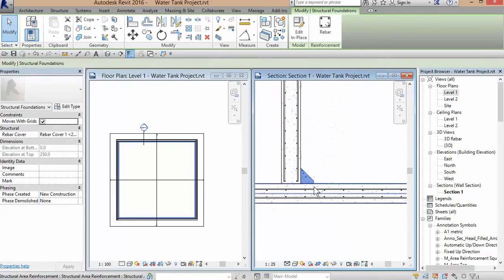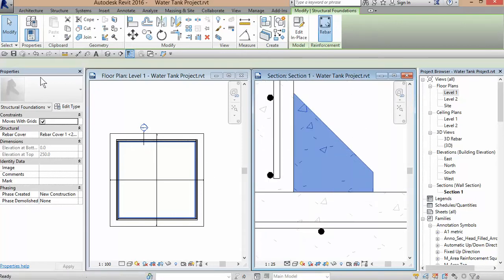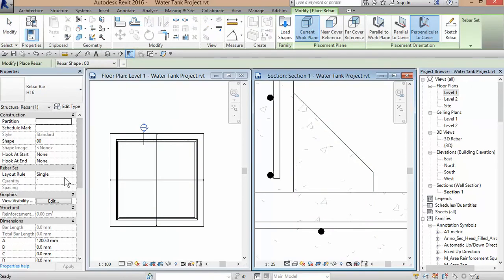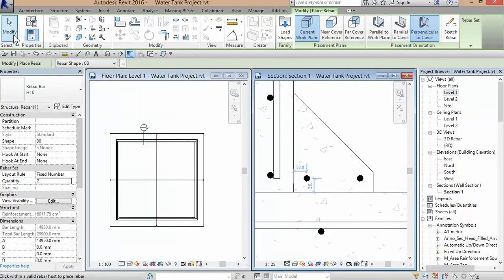any section, you can select. Now mind you, when I'm adding rebars to here, it's only going to be going along the top horizontal part and not straight around. If you choose, you could create sections and add the rebars along the full part, but for now I'm just going to do it along here, and I will only display the rebar here for documentation purposes. So select rebar, same 16 millimeters. I want 2 rebars, and they will be around here. Modify.